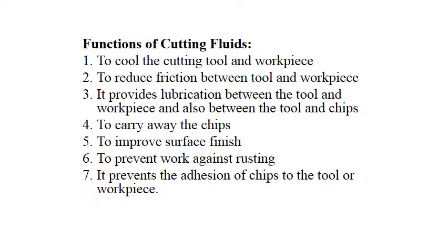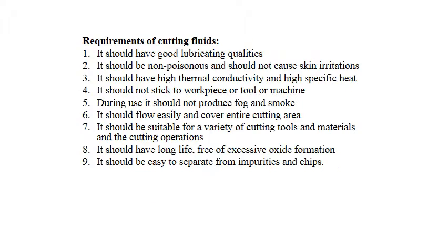So what is the function of the cutting fluid? To cool the cutting tool and workpiece, to reduce the friction between the workpiece and tool, to provide lubrication between the tool and workpiece, to carry away the chips, to improve the surface finish, to prevent the workpiece from rusting, and to prevent the adhesion of chips to the tool or workpiece.